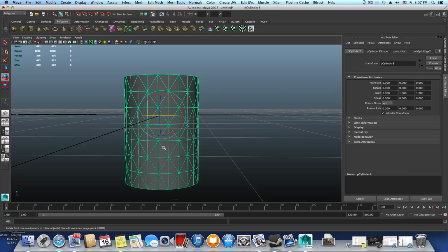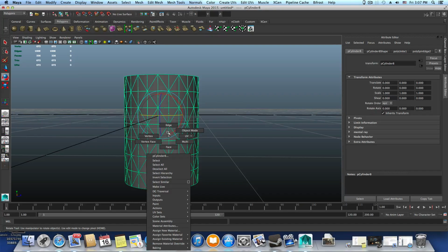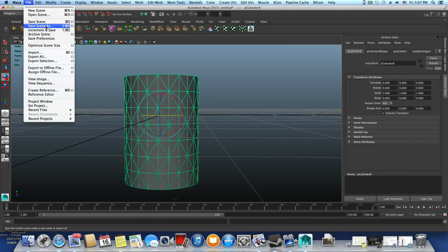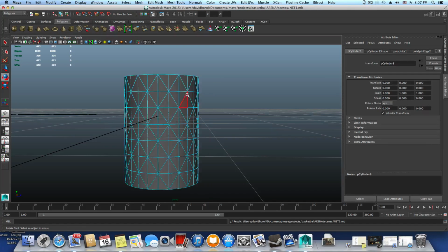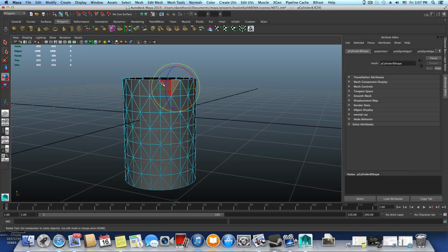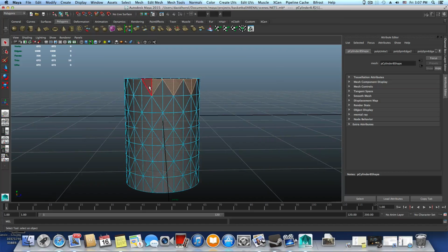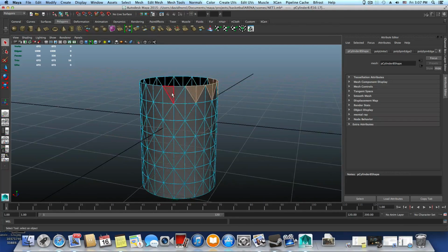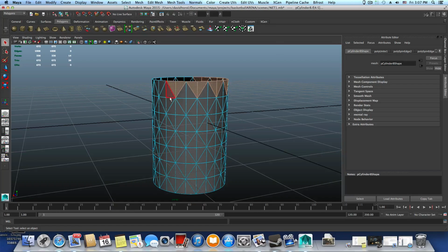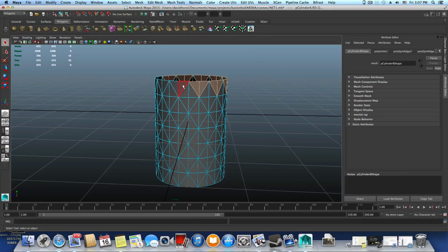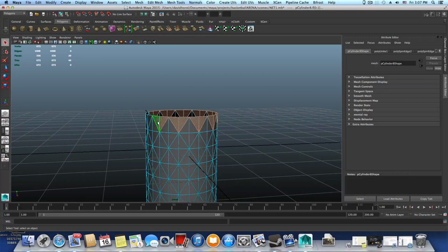And continue. Basically, why not? I should do this also. So I'm gonna save it as net1, okay? Save as. And right click, choose Face. I'm gonna grab this, switch to the Selection tool, because this gizmo of the Move tool, Rotation tool, and Scale tool is just disturbing. While you are on the Selection tool, you can't see it. Okay, so it's not in your way.